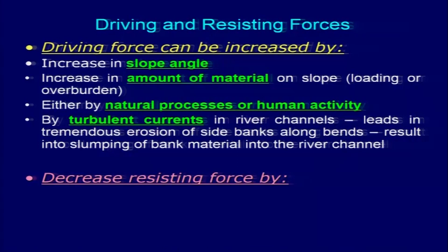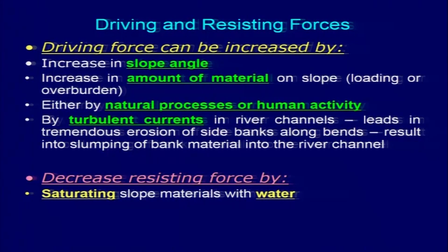Decrease in resisting force can be because of saturating the slope material by water. So, in most of the areas, what has been done is to allow the water to flow out, or run off, as early as possible.